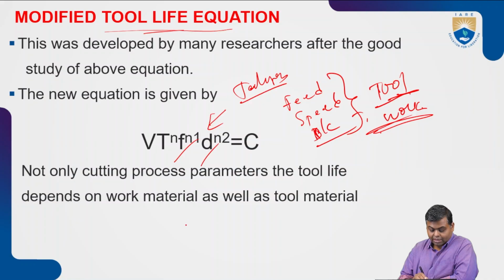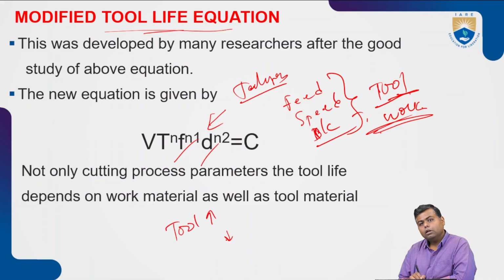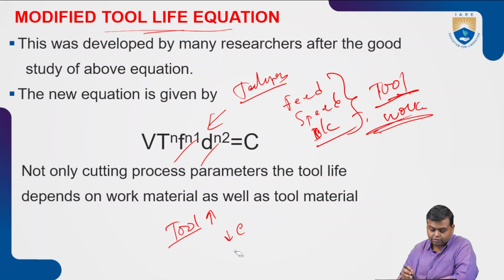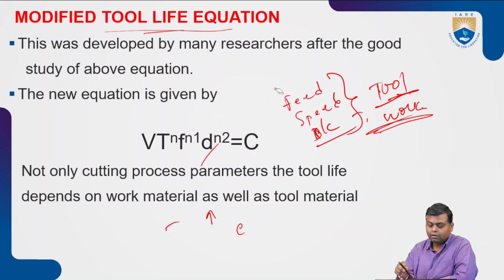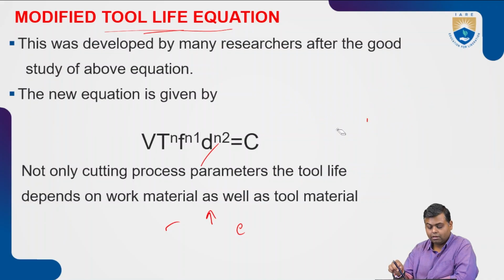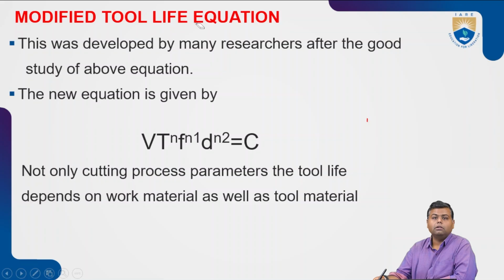In the machining process, the tool life should be very high. It should not be very low. If it is very low, you will not have economy in the cutting process. If it is not economical, the cost of machining increases, thereby the burden on the product selling price also increases, because the product will cost very high. So in general, we need to settle these things with respect to speed, feed and depth of cut. Then only can we find the proper tool life.